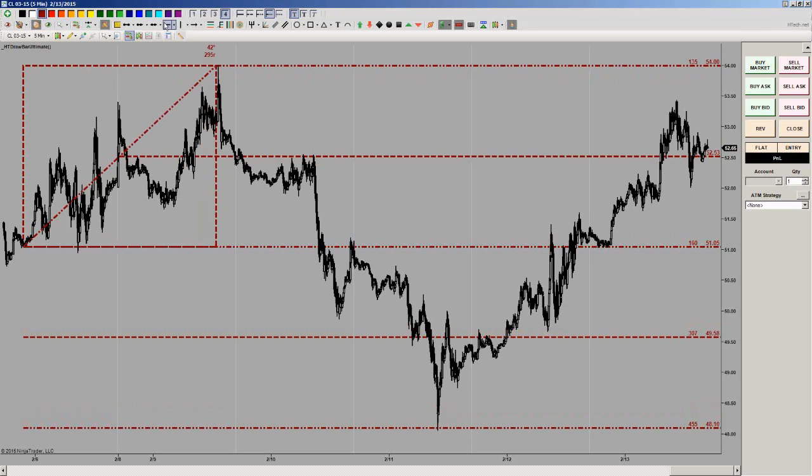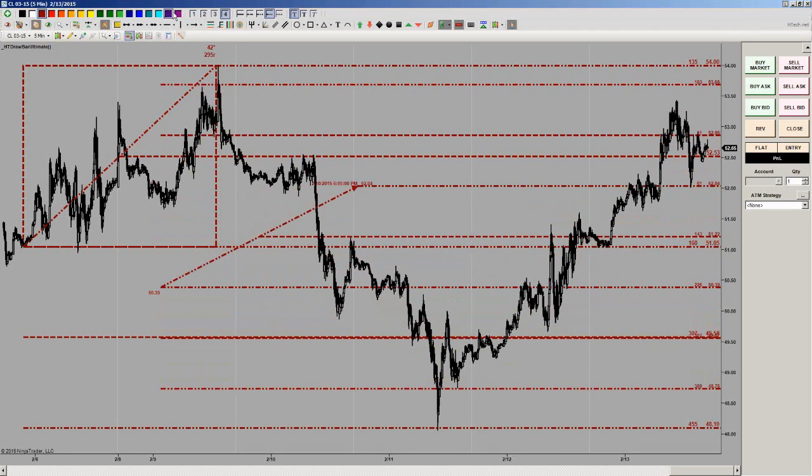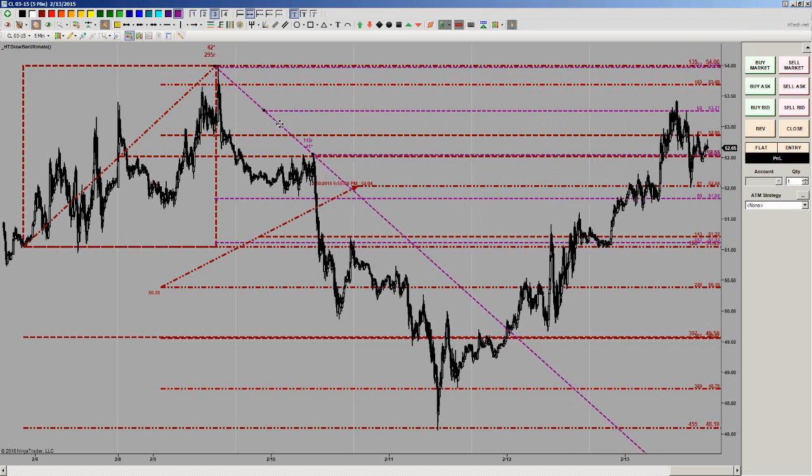So the color palette is also a style palette. It allows you to choose the width of the line, the style of the line, the color, and not just the line, but any draw object that I would select. If I want to change the color, change the width to 1, make it just dash, make it orange, and draw a ray. You can't really see that, so let's change that to a different color that maybe you can. Or maybe that's not big enough and we want it that way. Or let's just say that we want it solid.